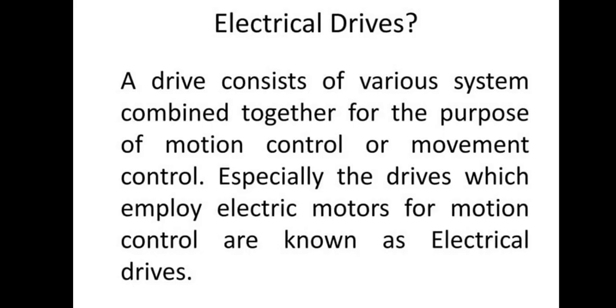In other words, an electrical drive helps us control the speed, torque and direction of an electric motor as per the requirements of the load. Generally, the electrical drive system consists of a few blocks. The basic and important blocks of the drive system are the power source, the power modulator or converter, the electric motor, the control unit, and finally the mechanical load.